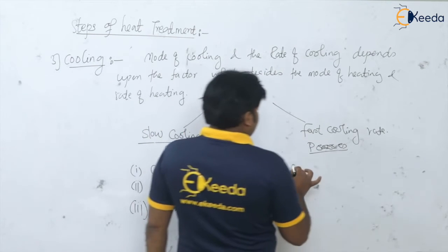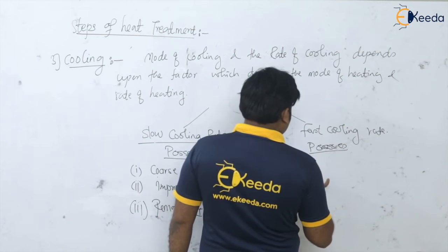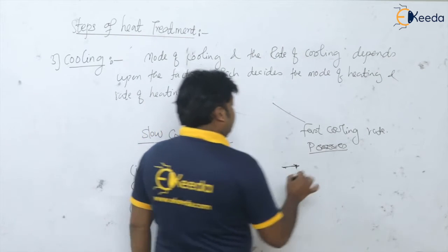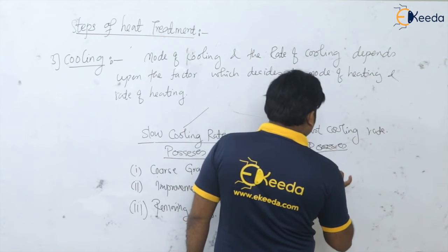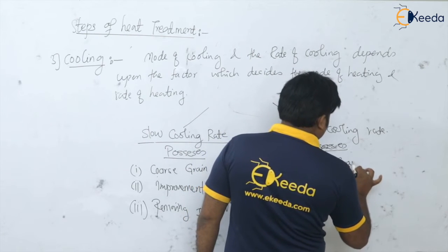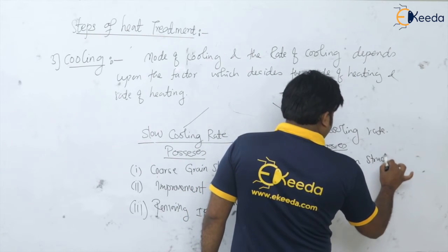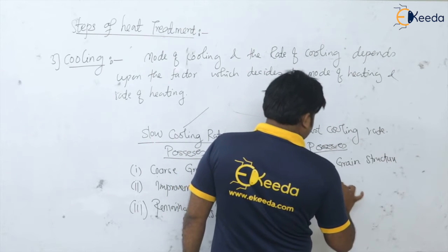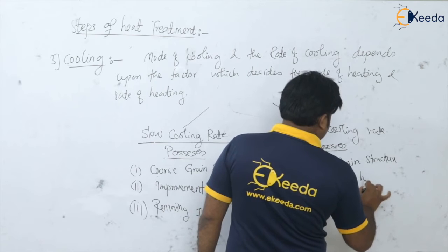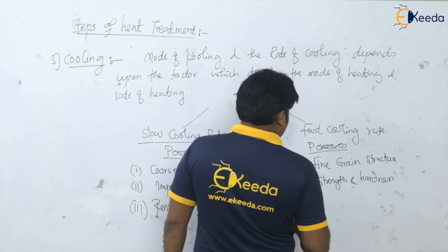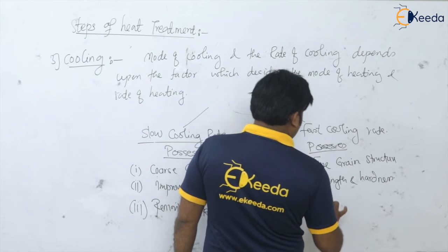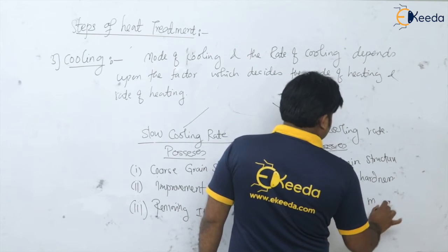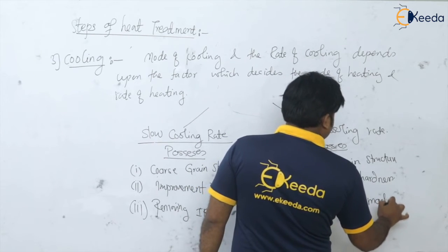And when we have fast cooling rates, we are going to get a fine grain size or grain structure, which will increase the strength and hardness, please remember. But it decreases the machinability.